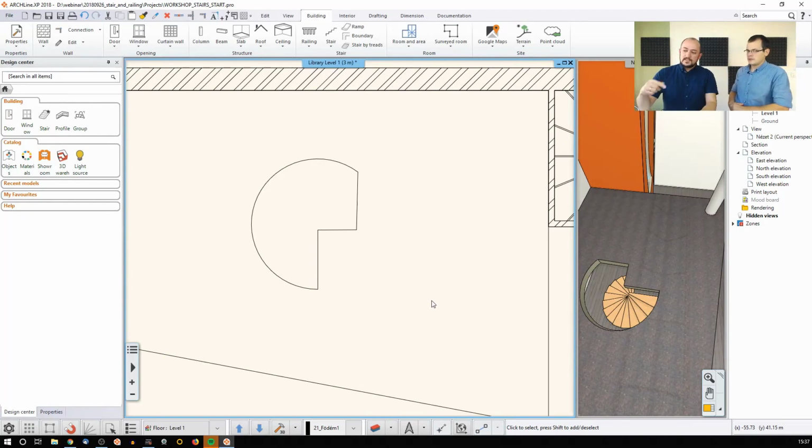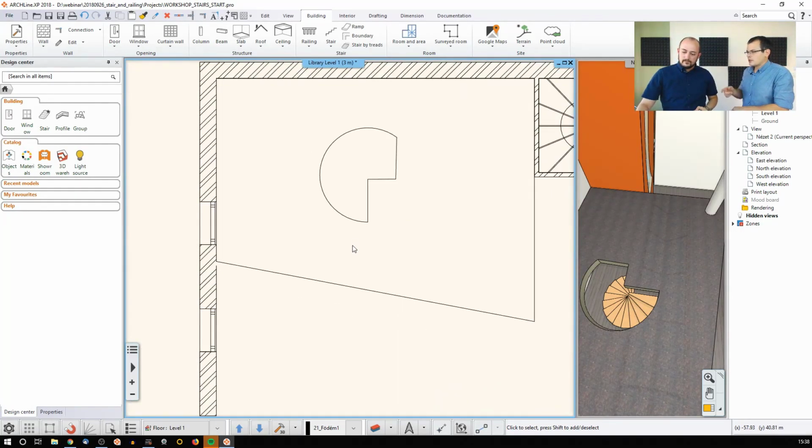The reason why the staircase was creating that cut above itself is because when you do that, this automatism is trying to use the staircase, literally stepping on the stair one by one and measuring a minimal distance. And if that minimal distance is not matched, and by default you can change that, by default that's 2.1 meters in the software. So that's something that is quite useful if a standing man would like to walk up the stair. And when this value is not matched, the software will automatically start cutting the hole and creating the cut above this staircase. What about connection to walls?